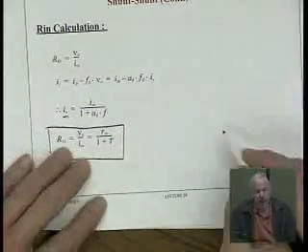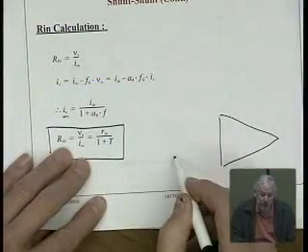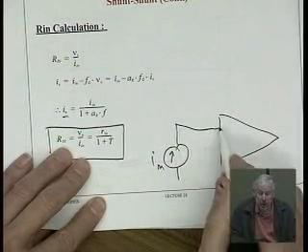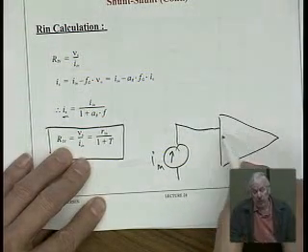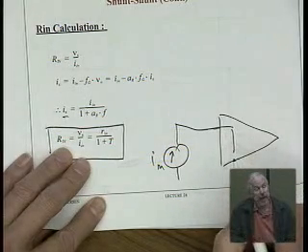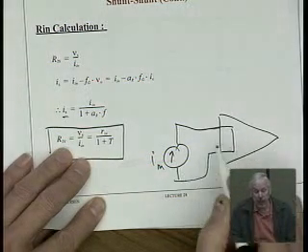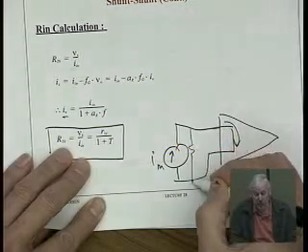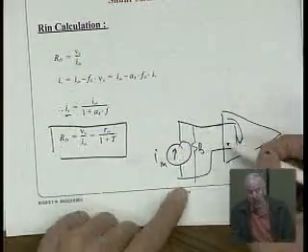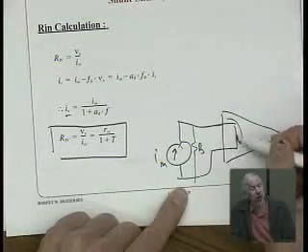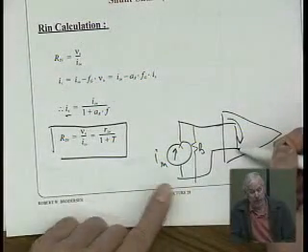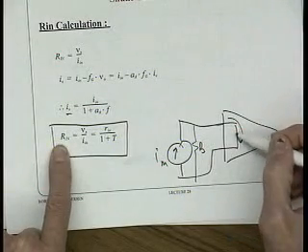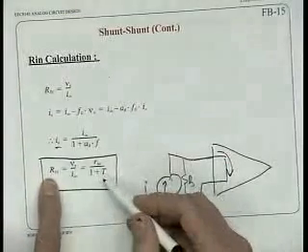And what would you like to have? Think about it. Remember, we have In, and this is going into an amplifier. What would we ideally like to have that amplifier look like? We'd like to have it look like a short circuit, right? We'd like all the current to go into the amplifier, because if we have some source resistance, a perfect current amplifier has a short circuit on its input. So sure enough, this gives us a low valued input resistance divided by the loop gain.